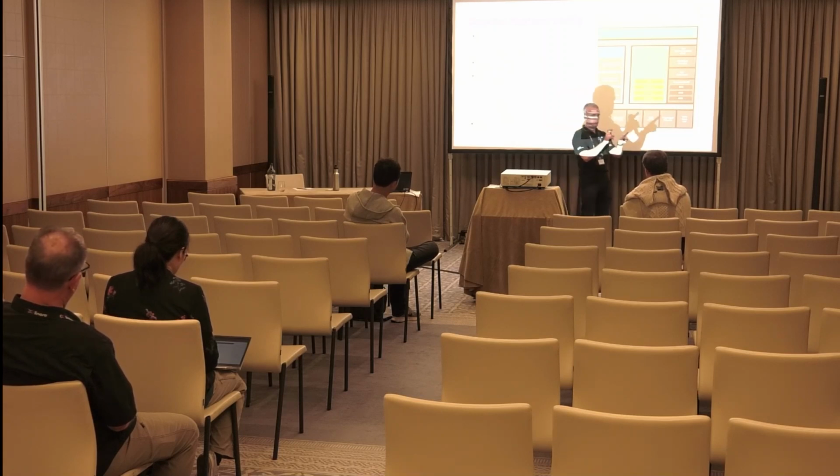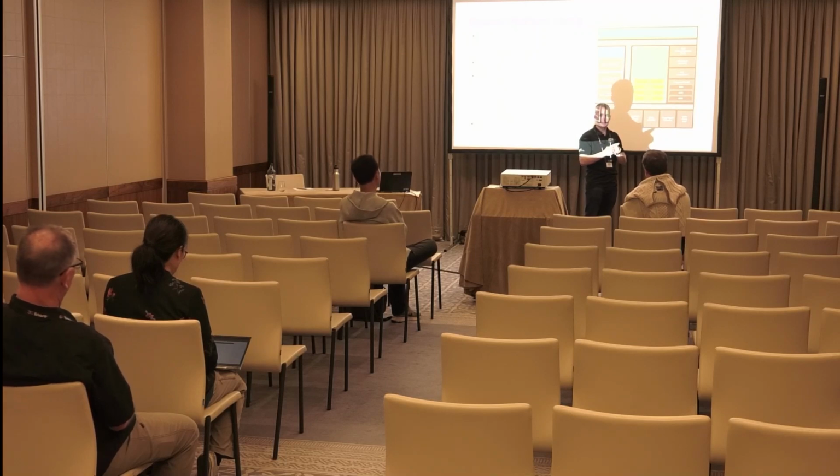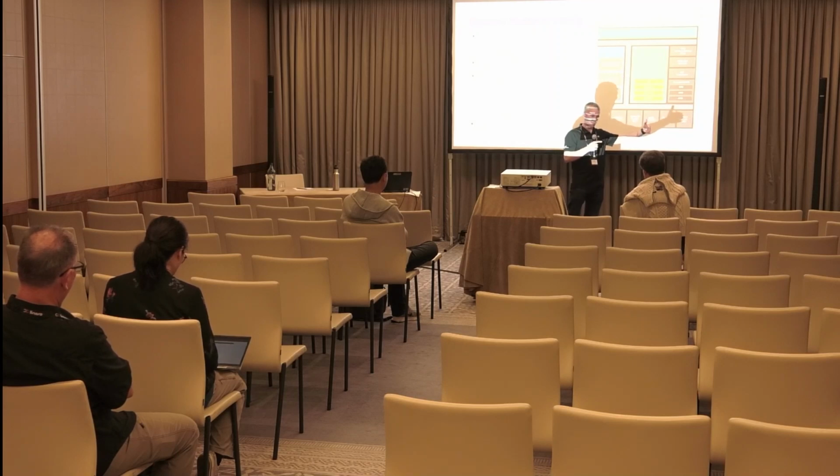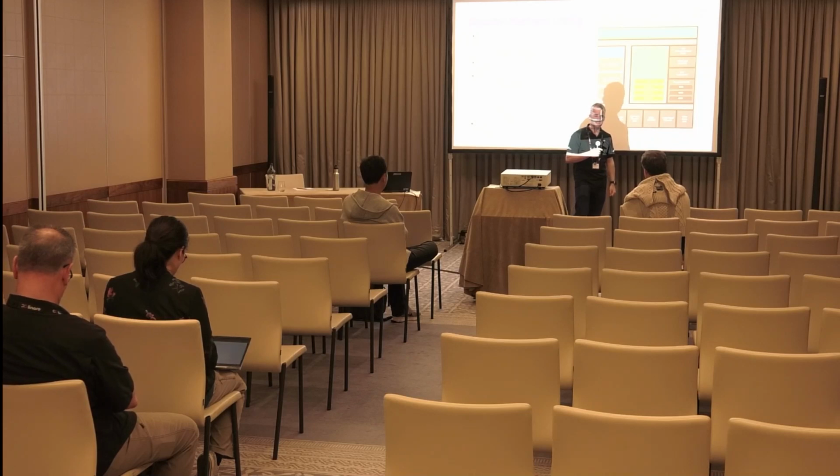So we always load a bit stream and a DTBO. They're always married. When I make that call to load initially, I'm loading a DTBO and the bit stream. So when I do an unload, I disable and pull out the DTBO that I just had in there. Then via what we call the PLM, the new bit stream will get jammed in through that CFI interface. Once that completes, the kernel side driver will then also load the DTBO with that bit stream. So that's basically the orchestration that happens.